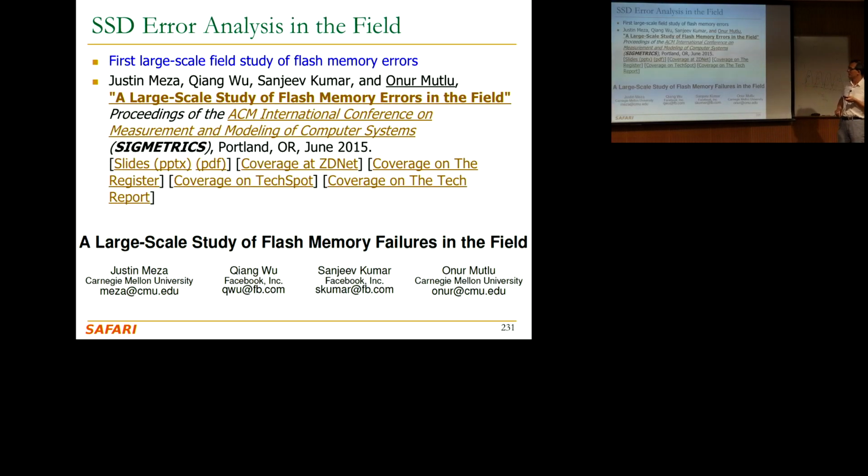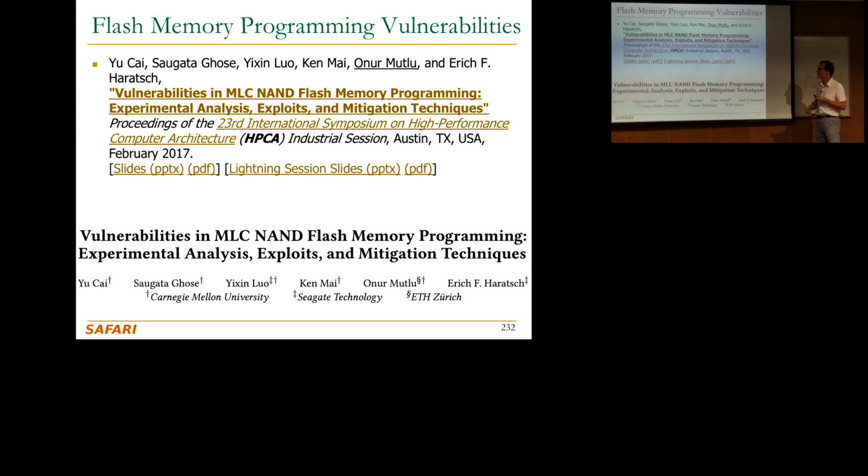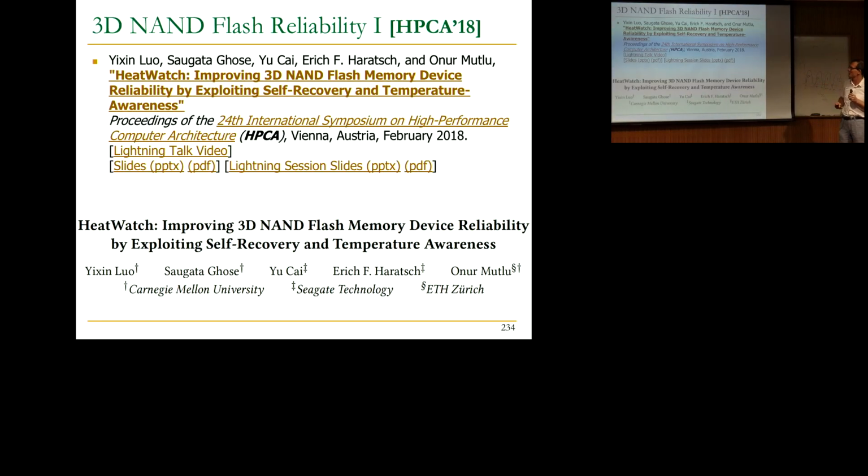Okay, we've studied also data retention. Data retention is actually really, really interesting. And just like we have disturb-prone and disturb-resistant cells, there are data retention-prone and data retention-resistant cells also, and you can take advantage of this. So there's a lot more over here. This is a more theoretical paper that actually does a lot of online flash channel modeling that I'm not going to talk about at this point.